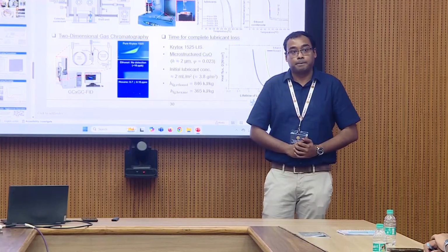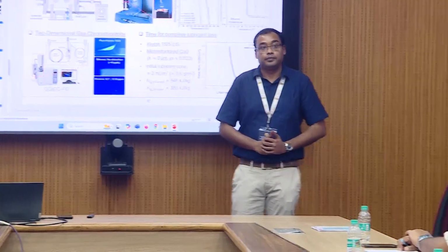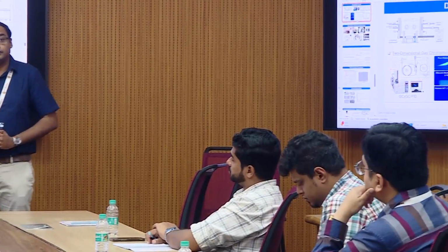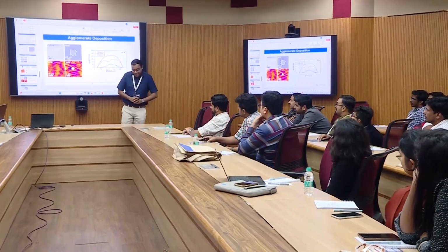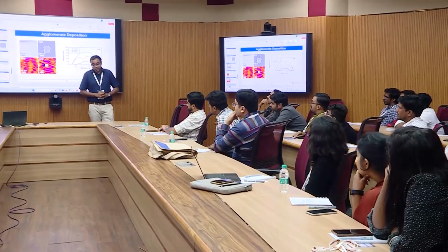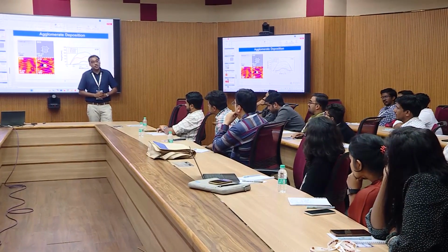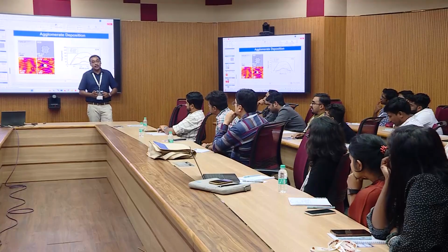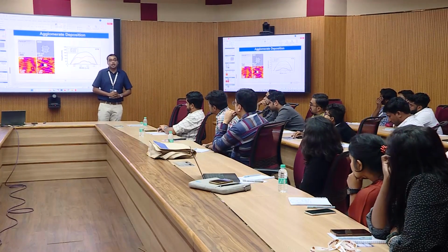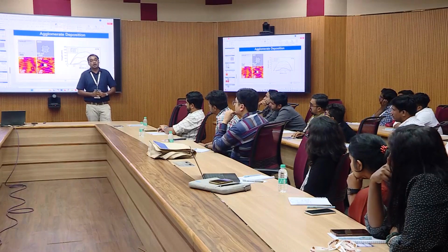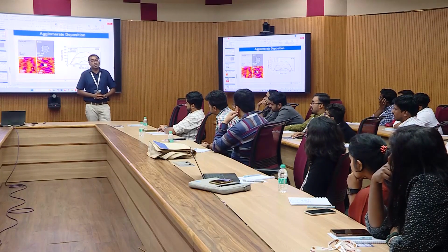Last question is, you showed that if you make a surface super hydrophilic and leave it, the contact angle keeps on increasing. Do you have a method of how to keep it super hydrophilic? So that's a very interesting question. We generally try to keep it submerged in water right after fabrication. It is not foolproof, but it does keep the superhydrophilicity for a longer time as compared to exposed in the air.